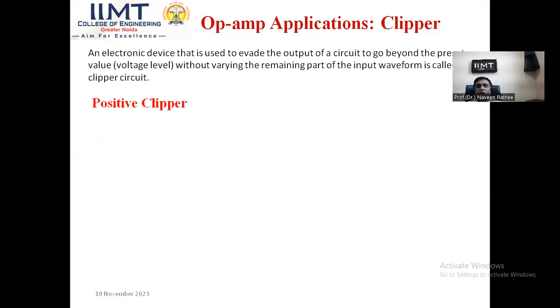So if I am clipping only the positive, now the new term has come, positive clipper. If I am clipping only the positive half of the input signal, maybe some portion or the entire positive waveform, then this circuit will be called a positive clipper, whereas the negative half portion will remain as it is. So that is a positive clipper.